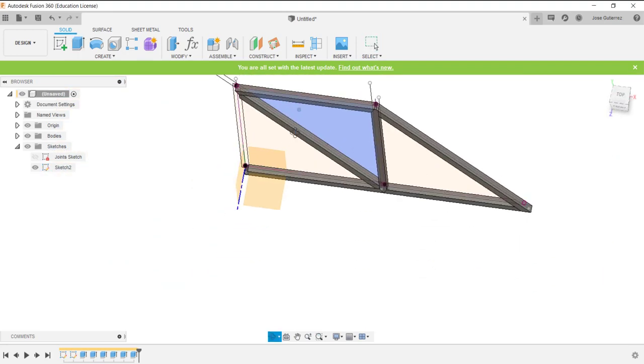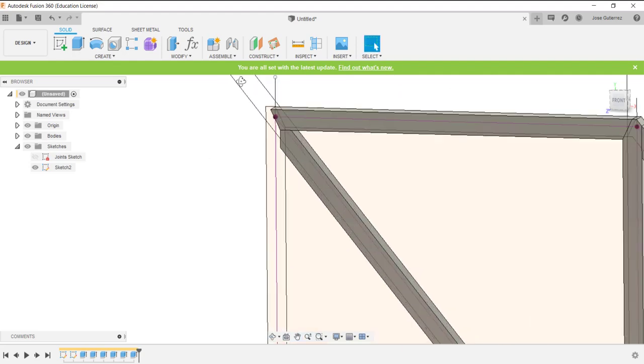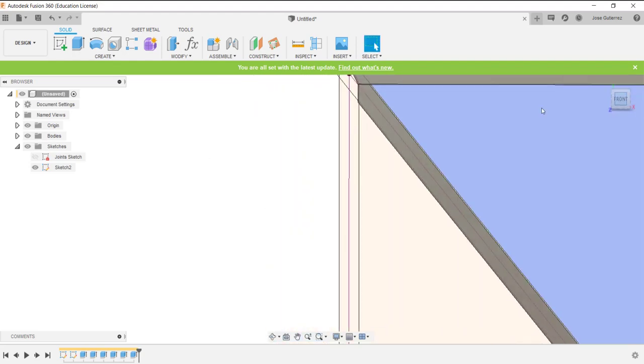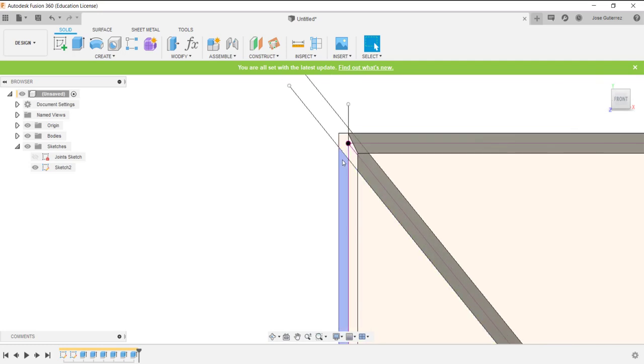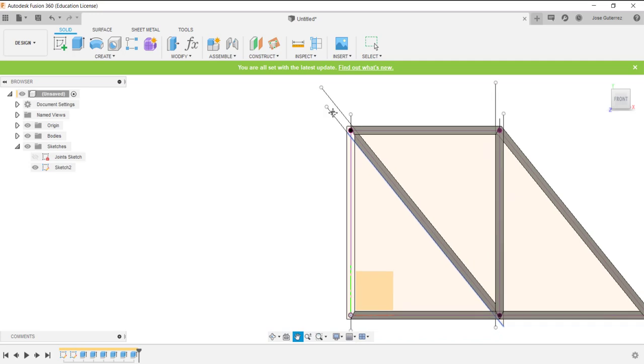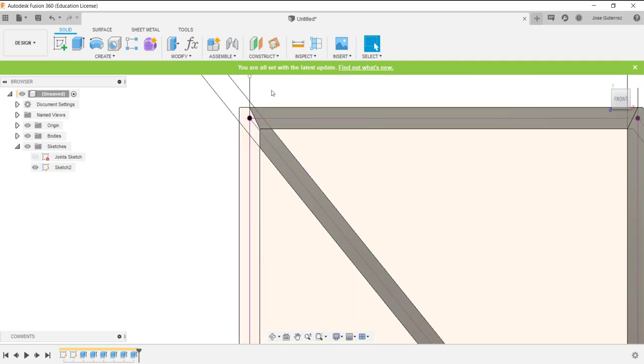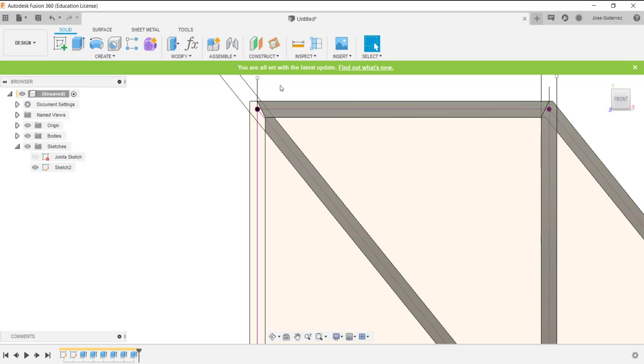On this last one, this is a little bit important here, we're not going to actually extrude the full thing. So let's go ahead and look at this from the front. Because we're only modeling half of the bridge, since we're going to utilize the fact that our bridge has symmetry, what you want to do is actually only extrude half of this member.